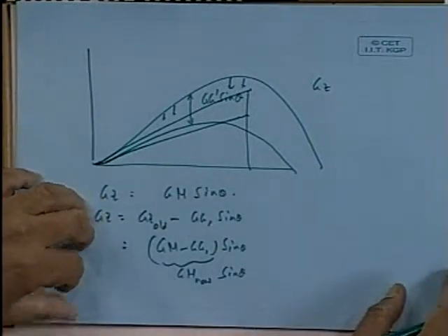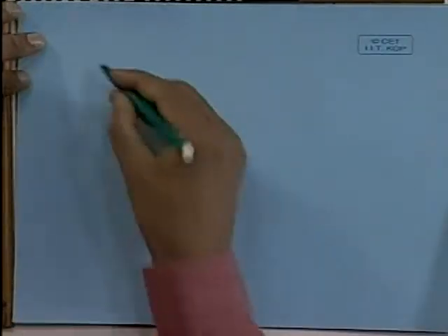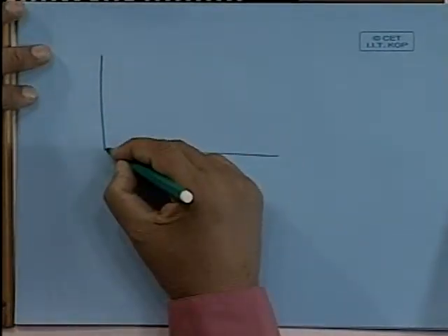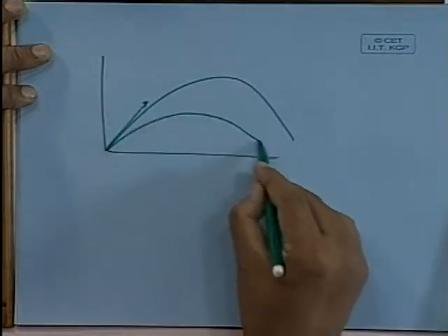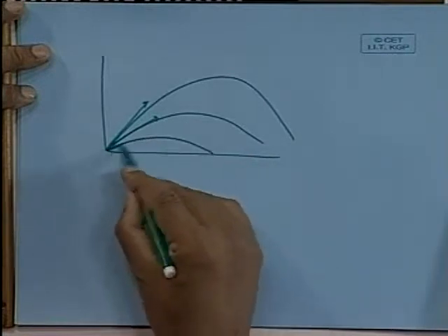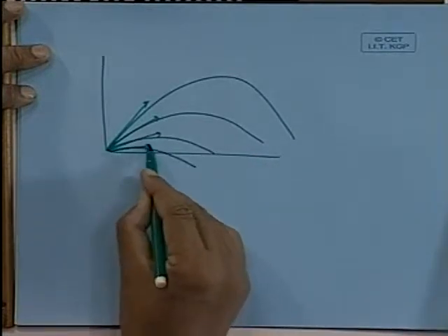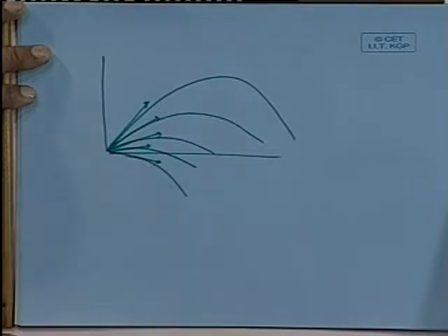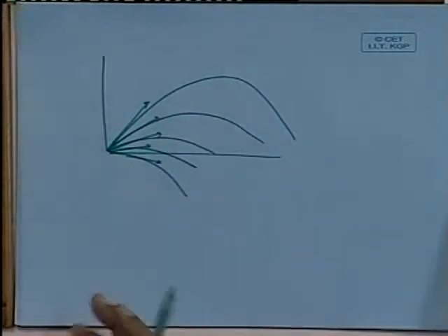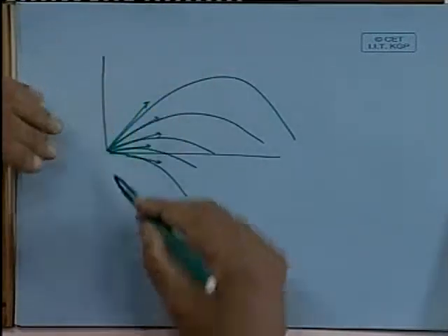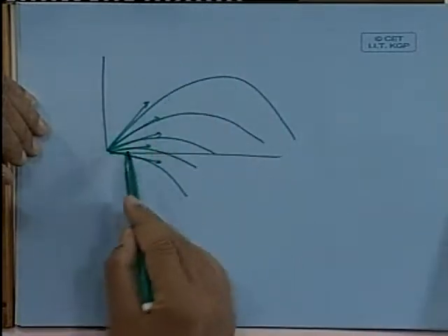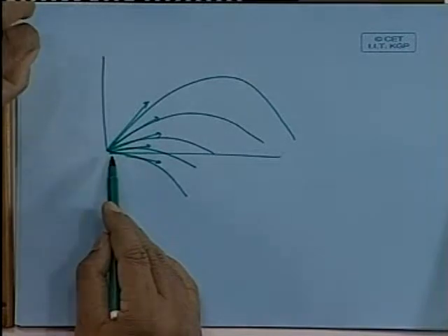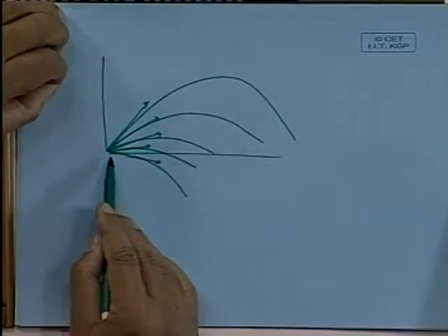This I will discuss in the next one. There are two things very important. Suppose the curve is just like this, not an S shape. Now the slope is this much. You bring it down, the slope becomes this much, bring it down, the slope is this much, bring it down, the slope is this much. So when this curve is there, and when you make GM negative by some means, at 0 degrees the slope has become negative because it doesn't have an inflection, it is just a parabolic curve. If the shape is a parabolic curve, the moment you make GM negative, it will completely sink.